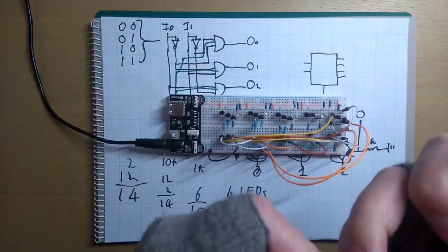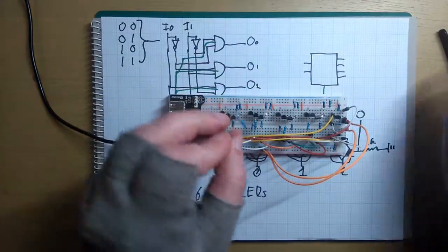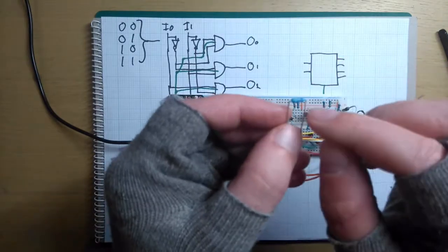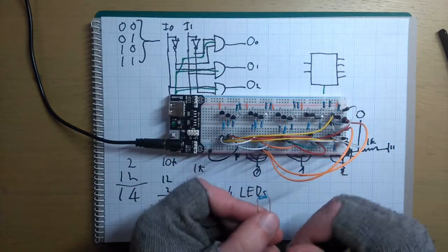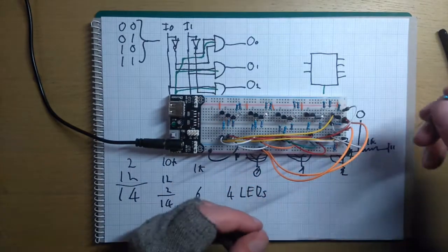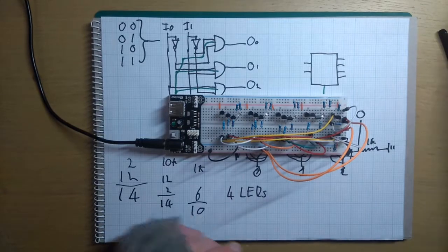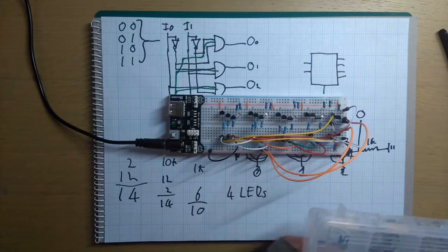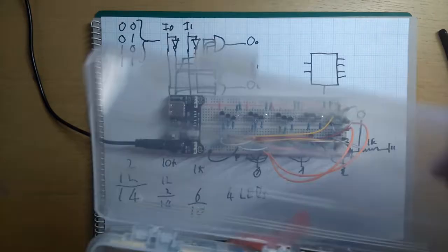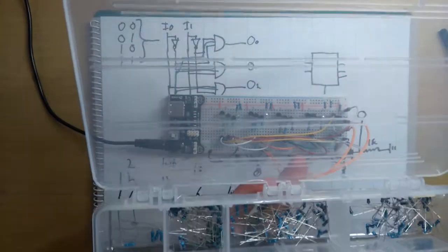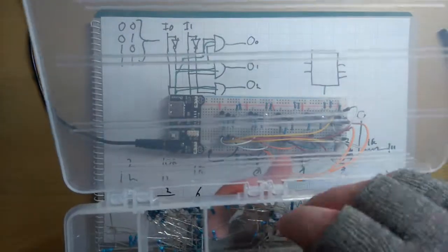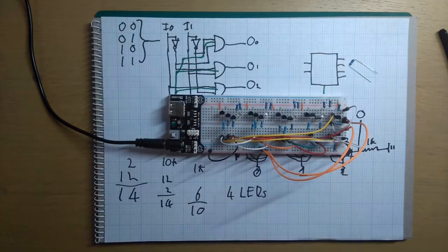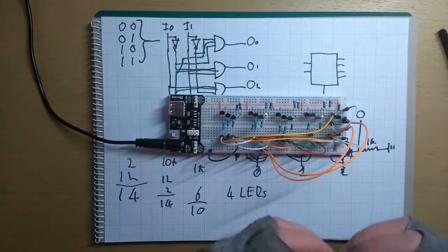It was this one. See, these were some of the original resistors I had, and the barcode marking on resistors is pretty ambiguous anyway, but these colors are really faded. It's hard to actually read them. So here we go. It's over here. Grab an actual 10k out of there. Let's put that back in the actual 220 slot, and grab a 10k. This is why you need a multimeter. Problems like that, really easy to solve with a multimeter.